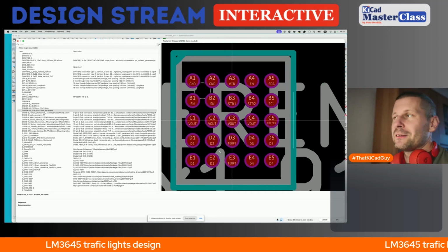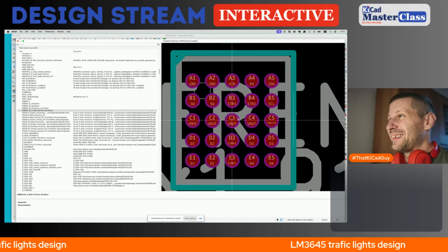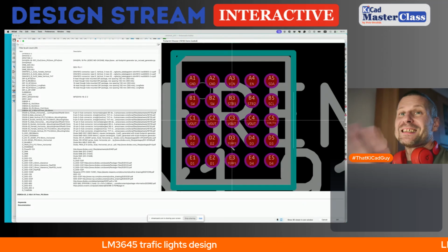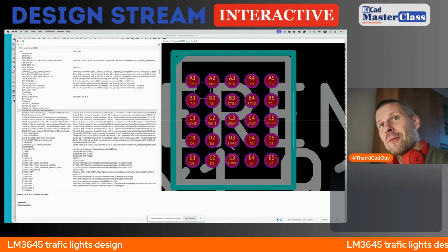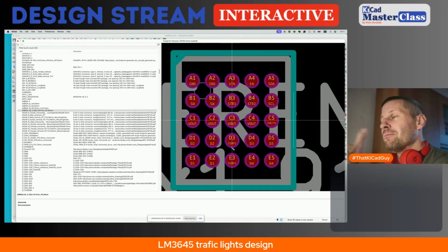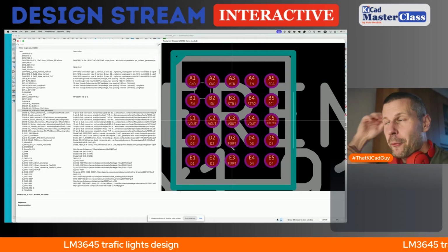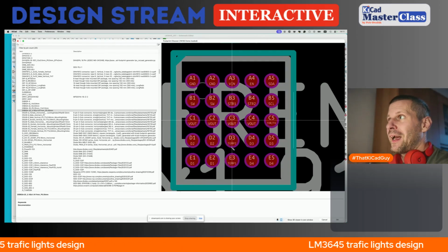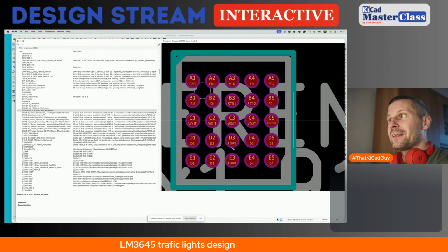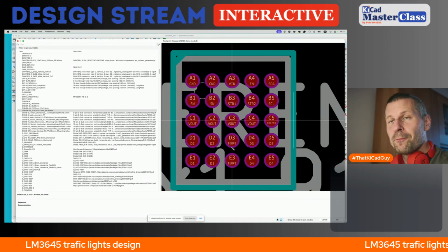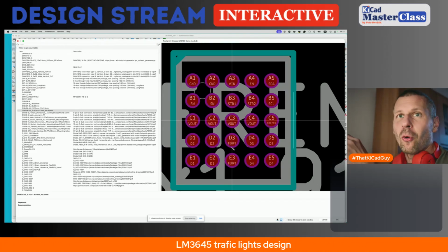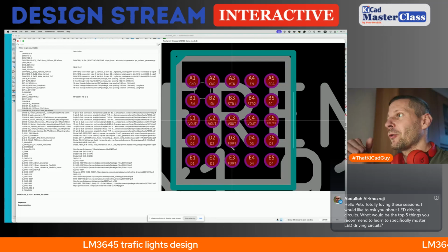And I verified in the datasheet that none of these 3 pads, strobe 1, strobe 2, and temp 2, is necessary to connect. So I can leave them floating, and by configuration of the IC, of course, there will be some issues when I program the IC, because at first I had to disable the functionality of these 3 pads, at least, especially for temp 2, which when left floating could make some false errors of the temperature sensing or temperature measurement.